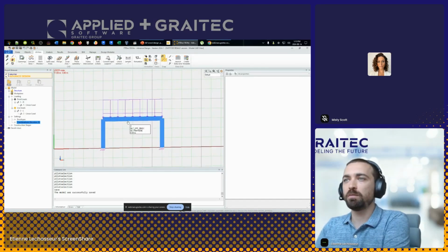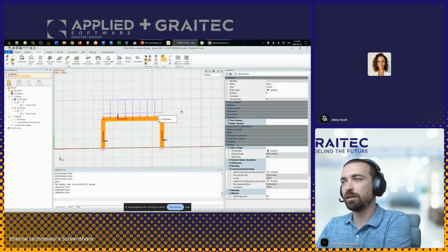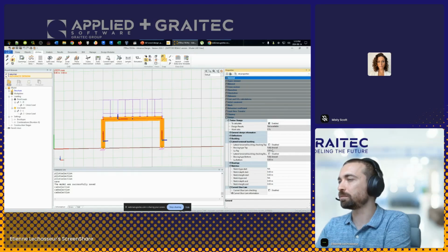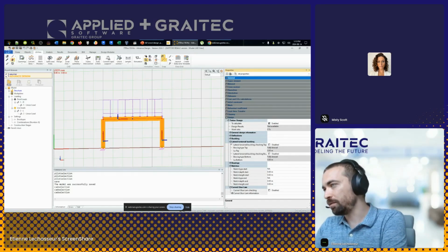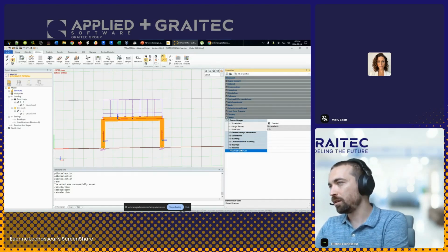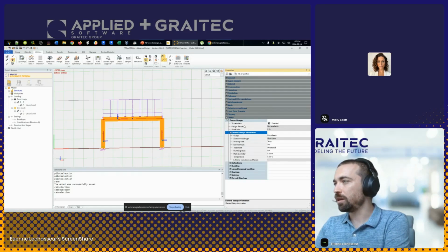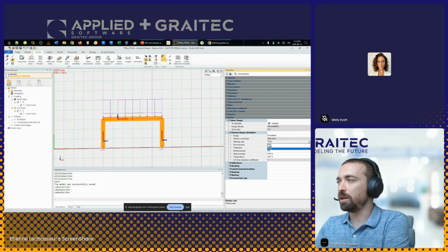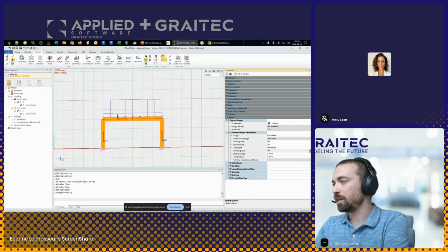Okay, so now if you want to look at the settings for the design, it's at the bottom of the property panel. We don't look at all of them right now. We'll come back after, but if we start with just some of the basics, this is where we would specify if we have a load sharing case, if the environment is wet or dry. We can also specify if it's treated or not. If we have built up sections, we also have a setting here for this.